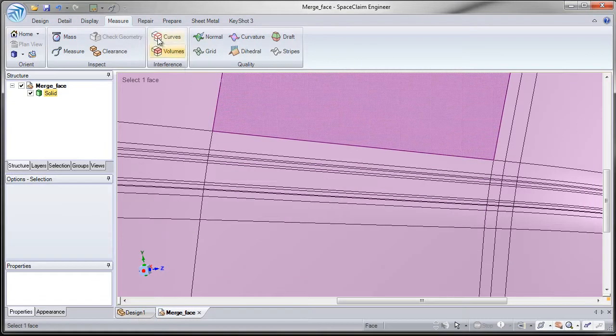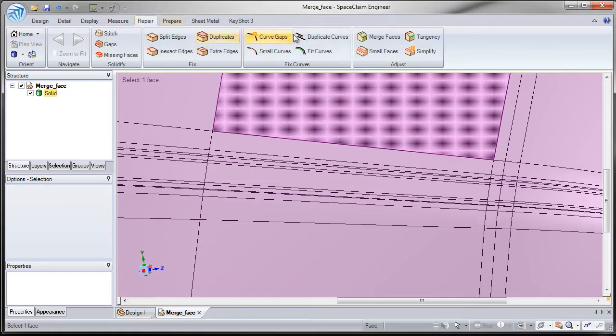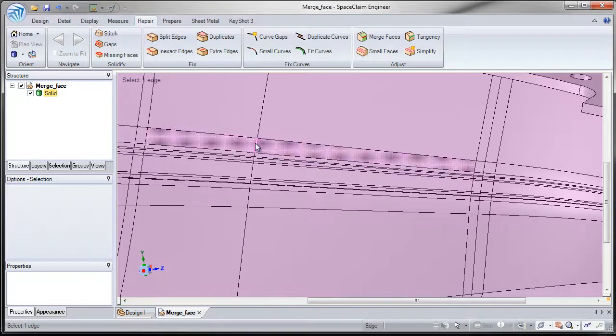So for this, we'll use our repair tool, Merge Face. How Merge Face works is it takes faces, say I box select this long face here. Notice on the right, it's hard for me to grab just what I want. Remember, you can always pause to pre-highlight what's being selected to make sure you only have selected what you want.